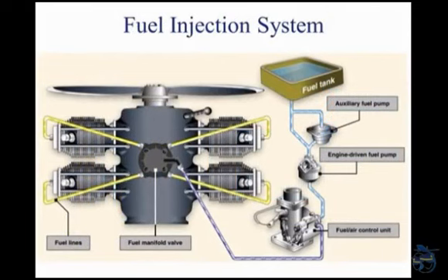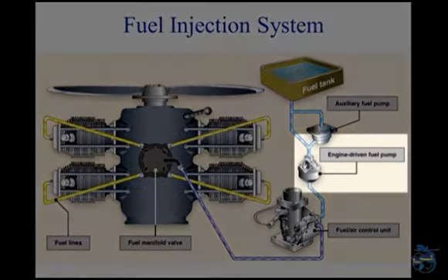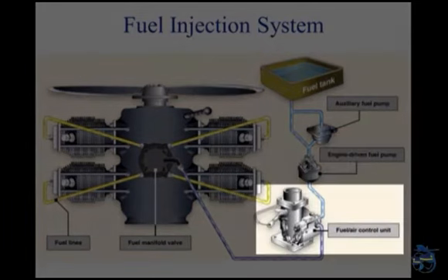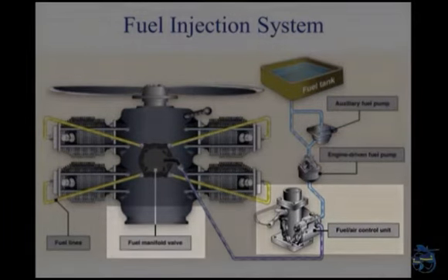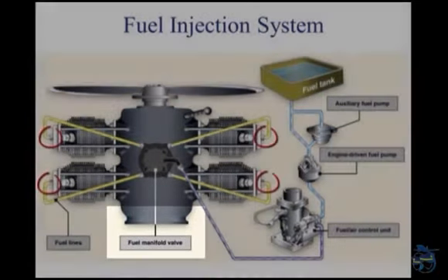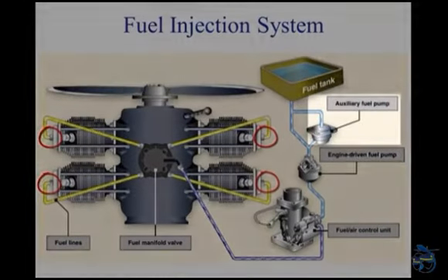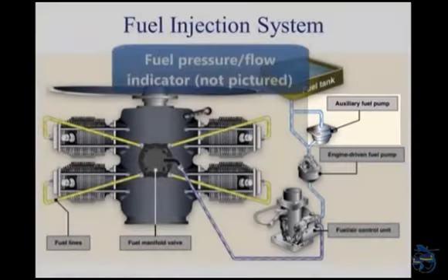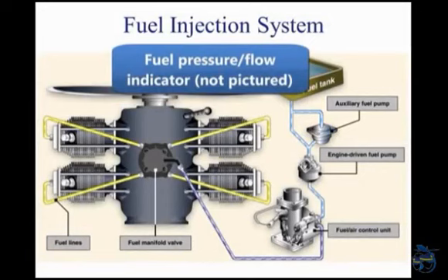the intake valve. The air intake for the fuel injection system is similar to that used in a carburetor system, with an alternate air source located within the engine cowling. A fuel injection system usually incorporates 6 basic components: an engine-driven fuel pump, a fuel air control unit, fuel manifold, fuel distributor, discharge nozzles, an auxiliary fuel pump, and fuel pressure flow indicators.